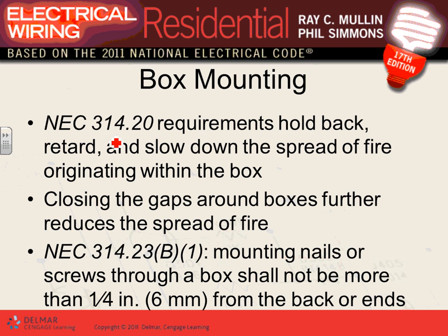Box mounting is required to hold back and slow down the spread of fire. So this article will tell you why we care about putting a box. It holds back, retards, and slows down the spread of fire. That's the major reason that we use it. Closing the gaps around the boxes reduces the spread of fire. That's why we want that 1/4 of an inch. Remember that 1/4 of an inch, to maintain not more than a 1/4 of an inch for non-combustible.